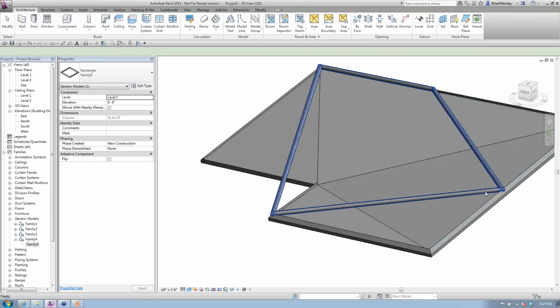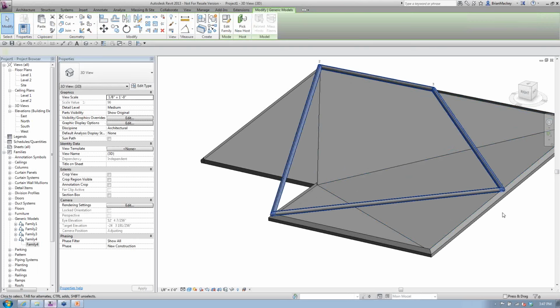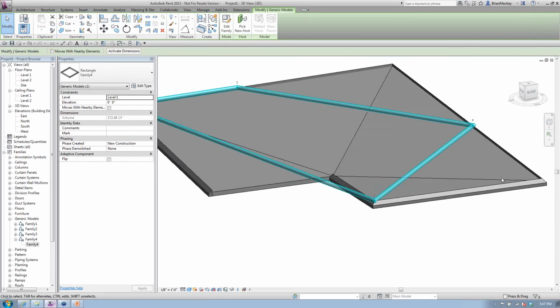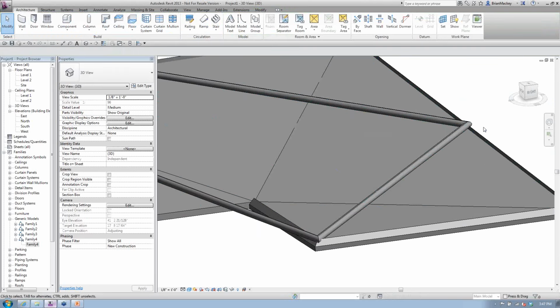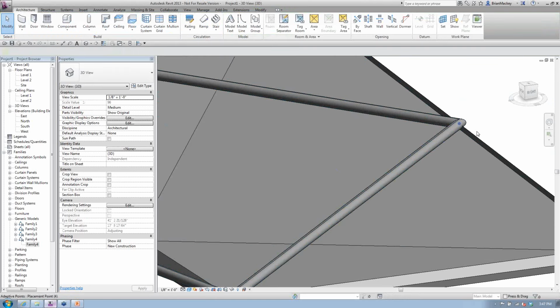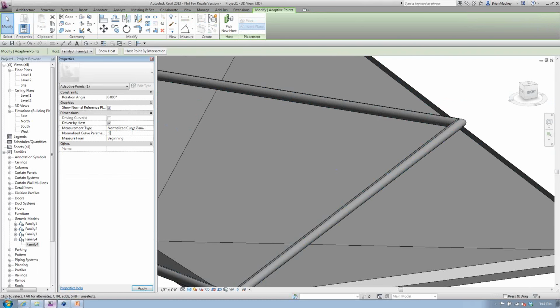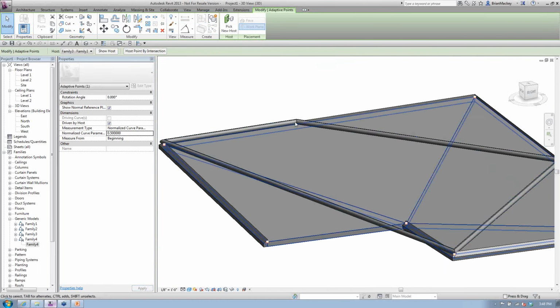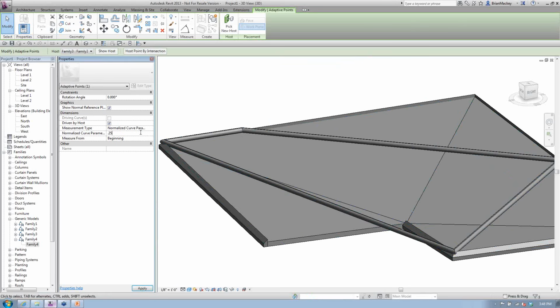So taking that tube frame construction, now I can really start to break this down, getting into more objects, start playing with those objects. And again, those points are hosted onto that object. So if I grab that point, I want it in the middle. I didn't snap to the midpoint. I can change its rationalization to be halfway through the middle. So as opposed to being at 0.5, let's move it 3/4 of the way through the middle. Or no, let's move it at 1/4 of the way through the middle.